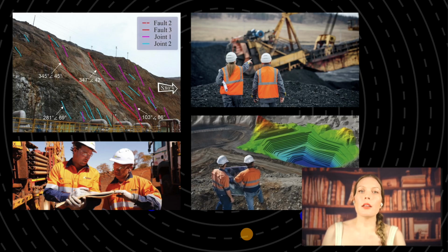So there are several ways to assess slope stability. The simplest are empirical and analytical methods based on engineering experience. In some cases, an engineer can estimate the allowable slope angle using analogs and reference data. For example, for loose field soils, published guidelines define maximum unreinforced slopes. Typically, it's around 34 to 37 degrees for dry, dense sand.